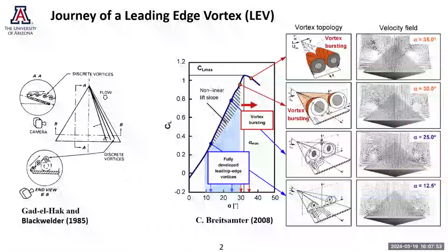This region experiences something called vortex bursting, wherein, by the traditional definition, the actual velocity of the particles in the vortex achieves stagnation. That is, their actual velocity goes down to zero. So air molecules or particles just go everywhere. A lot of researchers have focused on this region and used active flow control techniques to control this vortex bursting and extend the stall region to higher alpha, so you have a larger angle of attack for the flight envelope.